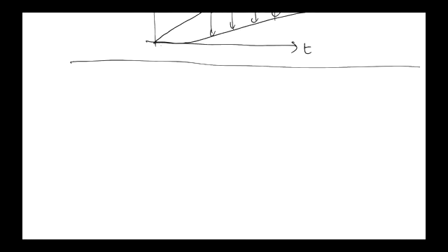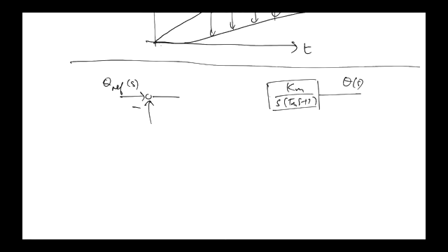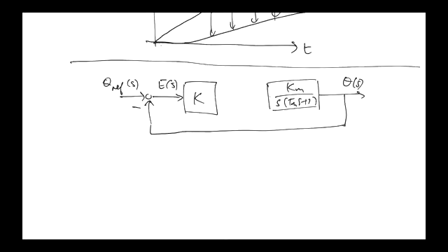So feedback control is not based on inverting the model. All right? The feedback control system that you built looks like this. It has theta ref coming in here. All right? It gets compared to a measurement of the angle, to produce the error signal, which we were looking at before, which goes into a constant gain controller, just a static controller, that produces the voltage into the motor.